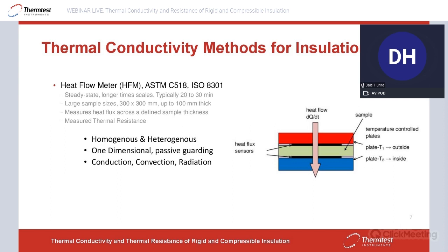The time it takes for steady state to be achieved matters because these types of additional modes of heat transfer or heterogeneity will negatively affect a transient measurement, where steady state is not the condition. Those types of errors are stabilized through the steady state approach. So you basically have a stable conductivity despite these material properties or material characteristics that can affect other measurement approaches.